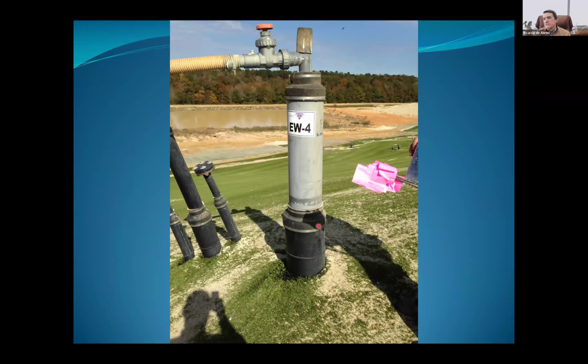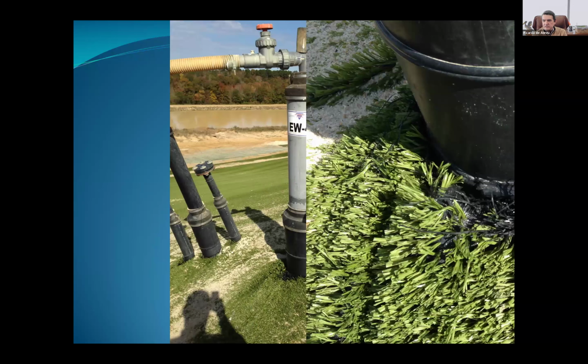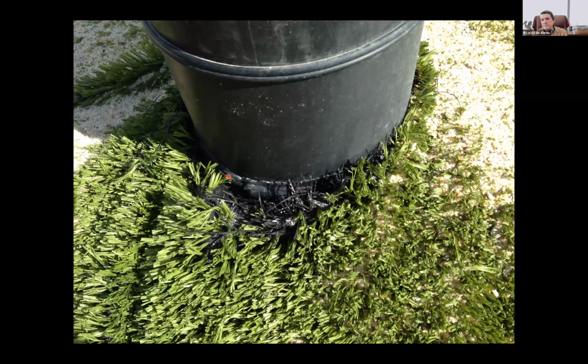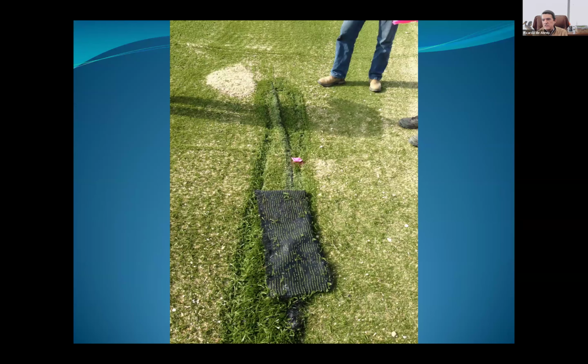We had several of those already there in the landfill at the time. So this is something that you have to look at closely whenever you're installing. In this particular case, you have a little gap here, but this is important. It's a detail, but it is important. Sometimes air gets trapped inside and it may lift up your geomembrane. So small things like that, we took a closer look at during CQA.